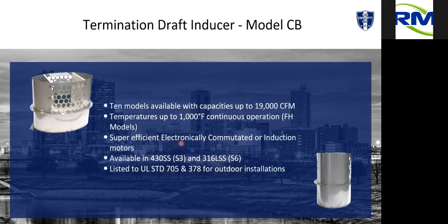Our termination fan goes up to 19,000 CFM. We don't sell a lot of 19,000 CFM fans, but if you have one, we'd love to help you with that. It is rated for 1,000 degrees. So for high temp applications, we talked about UL 103 being listed at 1,000 degrees. If you have a high temp stack, we recommend using a high temp fan.